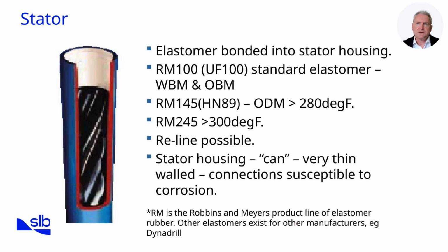The stator is a critical part of the PDM, serving as the stationary component of the power section. It consists of a steel housing with elastomer bonded to the inside surface. This elastomer forms the sealing surface against which the rotor turns. Several elastomer types are available to suit different drilling environments. For example, RM100 elastomer is suitable for water-based and oil-based muds under moderate conditions, while